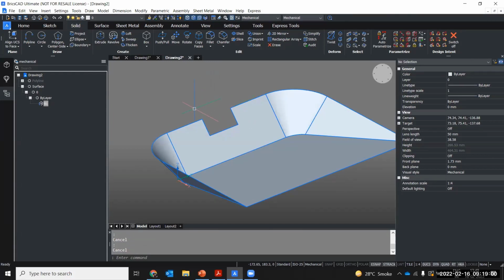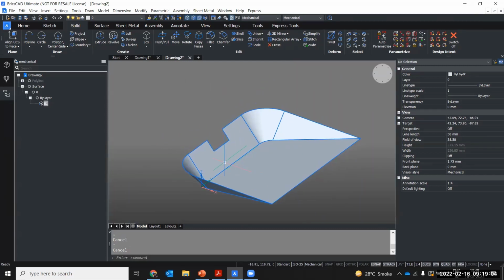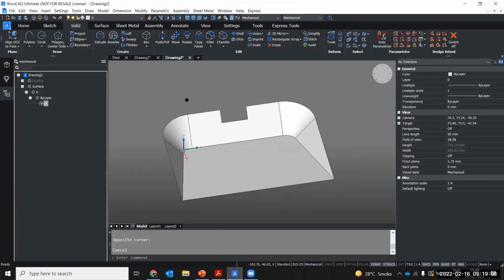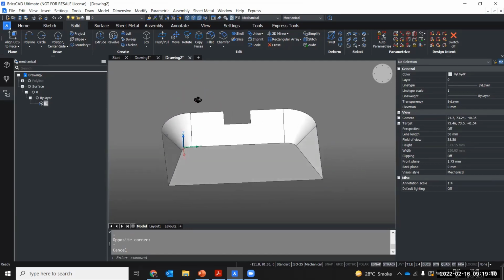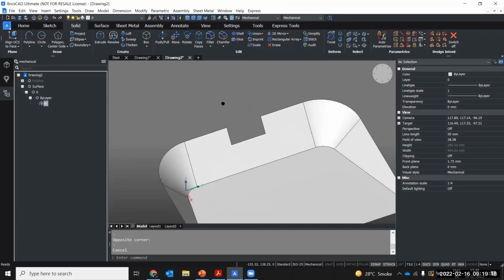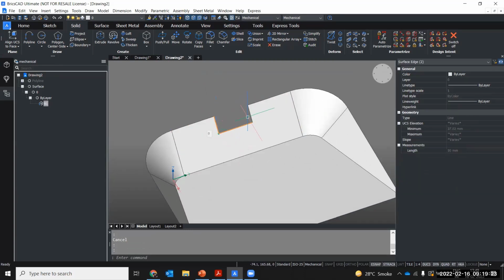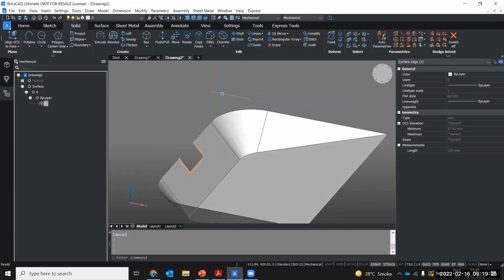Okay. Now the next thing, you need to create a handle for your geometry. So what you need to do is simply change the orientation, go to your blue selection box, and simply select the edges this way, or you can also select them manually. So for example, I'll just select these three edges manually.